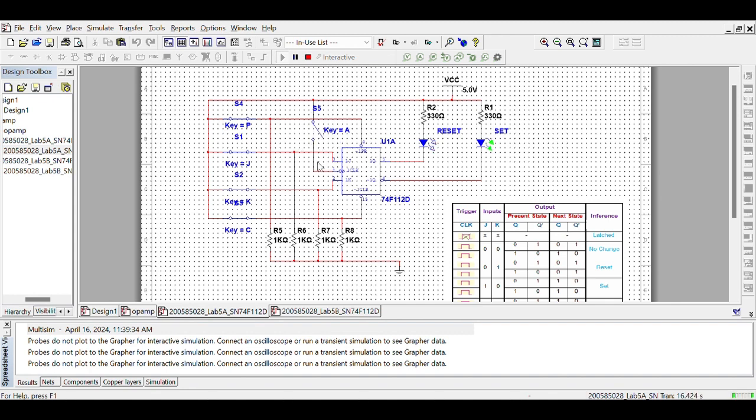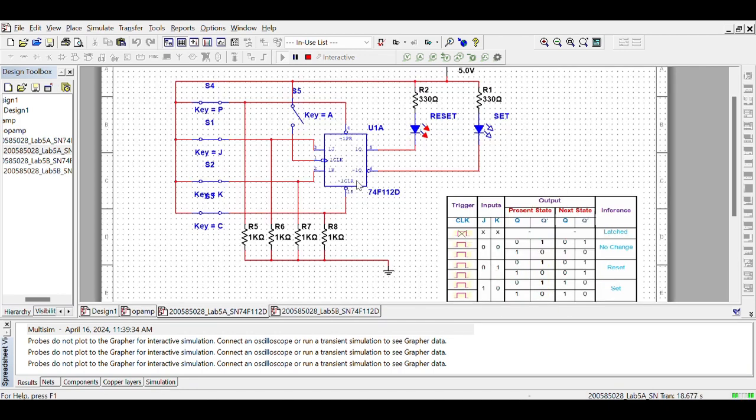So basically what this means is, here it's in a closed state, so we can treat that as high since it's getting the power signal from VCC. So what's happening is when it drops low, that's what's triggering the change. So it's that falling edge that is actually triggering the clock here and what's being picked up to actually actuate the JK flip-flop. So that's enough of this one.